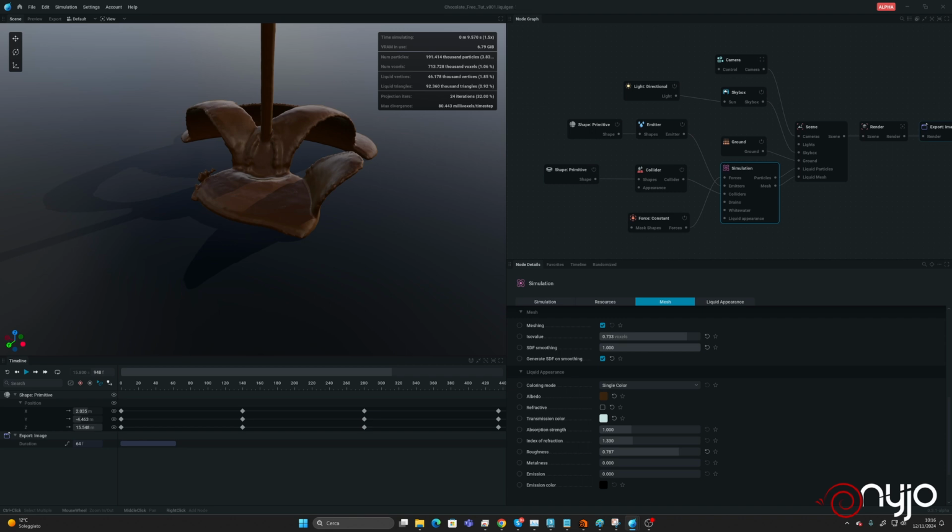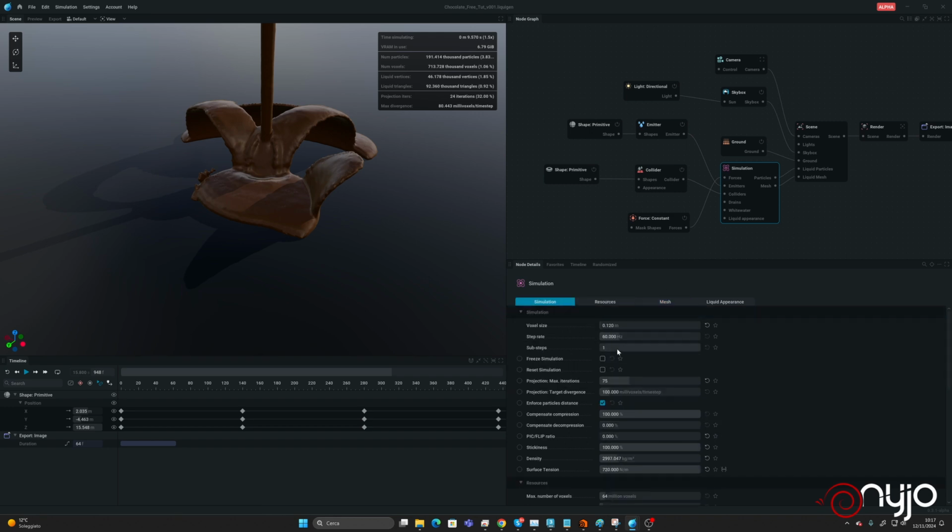So how can we play to have a better result? Something more that needs to be tweaked when you have a fluid that is highly sticking over the surface, that you like to have with more dense effects and a very high viscosity. You can simulate something like that by going, for example, inside the simulation and saying that you need a higher number of substeps.